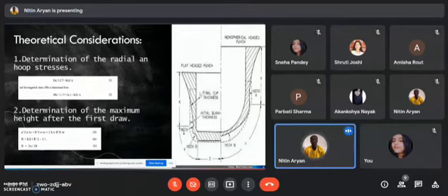the work in this process, and the work of the other researchers, applying the constant volume principle in plastic deformation we get a^2 π = b^2 π + 2πbh. Simplifying this, we get, where r is the drawing ratio, r is equal to 2a by 2b, and height h is equal to b by 2 of (r square minus